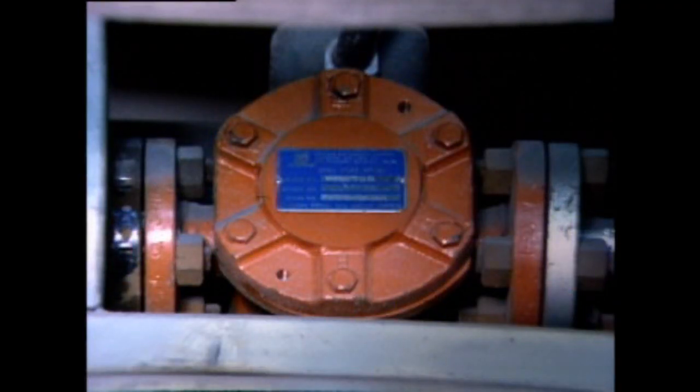This principle of operation is sometimes called positive displacement, and it involves measuring individual amounts of fluid so that a total flow value can be determined. Since these types of meters in essence measure fluid flow directly, we'll refer to them as direct flow meters. This oval gear meter is one example of a flow meter that uses positive displacement to measure total flow.